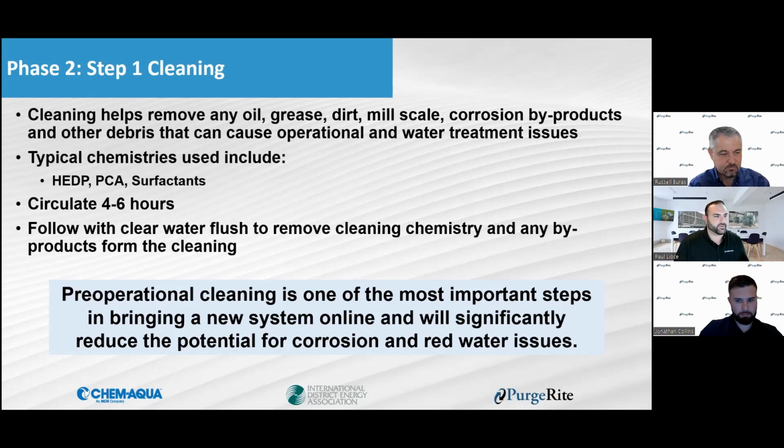But yeah, going on this one, step 1, the cleaning, is the most important. The velocities matter, as Russ was saying. If you try to flush this with a garden hose, not only are you going to be there for weeks on end, but you'll probably end up doing more damage in the long run. So really just following those steps and having a good plan in place beforehand.